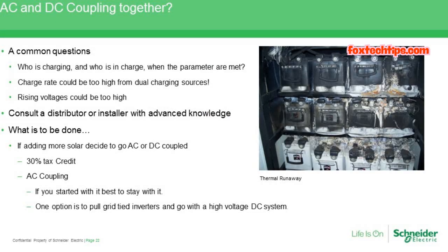So again, this time with an SW, things are fairly similar, which is nice with the Schneider product line, that both the XW Plus and the Connext SW share some basic building blocks and basic principles. So again, to remind you, with the SMA, SolarEdge, or Enphase, make sure that you reach out to the manufacturer to make sure that the inverter has frequency shifting, so that we don't run into a situation where we may accidentally overcharge the batteries. That would not be good.